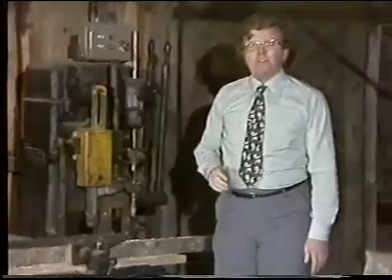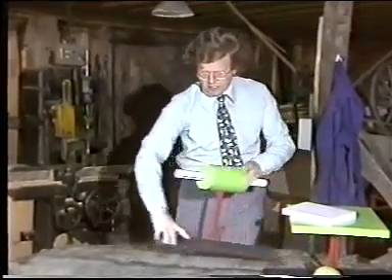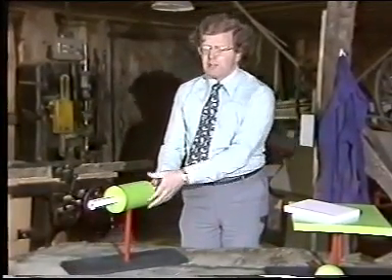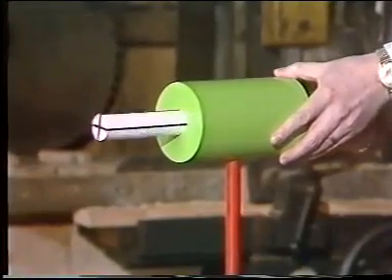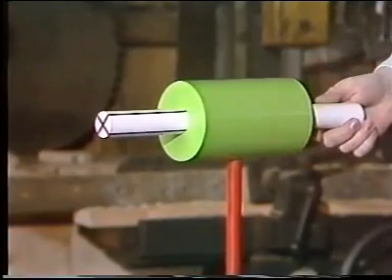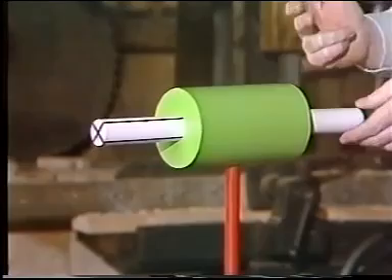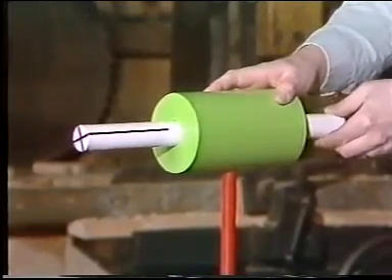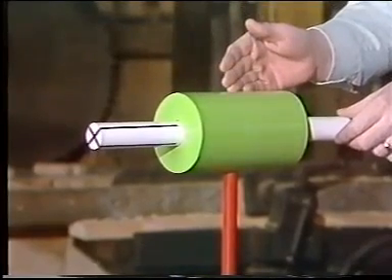And on our model of the cylindric pair, you can see that this joint, in fact, acts like a combination of the prismatic pair that allowed sliding and the revolute pair that allowed turning. So now I've got two motions on this joint. I've got to give two parameters to specify the position of one link relative to the other, the amount of sliding and the amount of turning. And so the cylindric pair has 2 degrees of freedom.